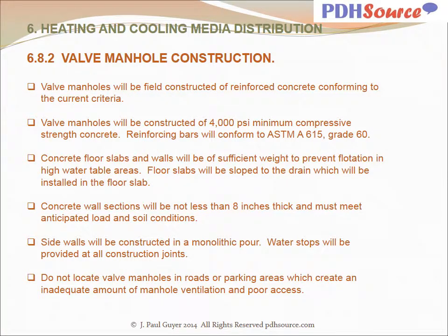Valve manholes will be field constructed of reinforced concrete conforming to the current criteria. Valve manholes will be constructed of 4,000 psi minimum compressive strength concrete. Reinforcing bars will conform to ASTM A615 grade 60. Concrete floor slabs and walls will be of sufficient weight to prevent flotation in high water table areas. Floor slabs will be sloped to the drain which will be installed in the floor slab. Concrete wall sections will be not less than 8 inches thick and must meet anticipated load and soil conditions. Side walls will be constructed in a monolithic pour. Water stops shall be provided at all construction joints.